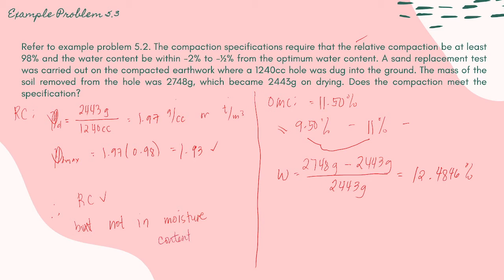Since our calculated moisture content is greater than the specified, we can say that it is wet of optimum.